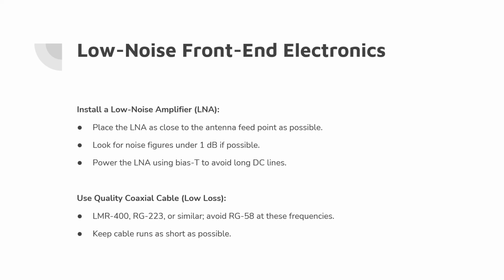It's not at the end, not at the side of the cavity, but at the very back of the cavity, and it protrudes into the cavity. It has a small servo motor, so the little dipole can turn 90 degrees to change the polarization, because satellites put out two signals, horizontal and vertical polarization, at least the old C-band satellites. And so it had all kinds of cables running to it.